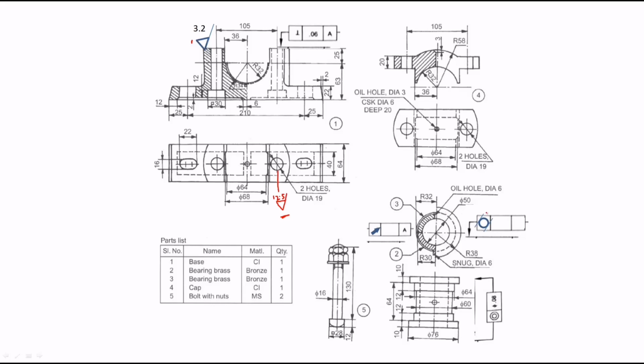So this is the way of indicating surface roughness symbols, surface roughness values, tolerance symbols, and preparing the process sheet and also the type of fit table. This is the total about the component drawing. Finally, we can call it the production drawing of the plumber block.